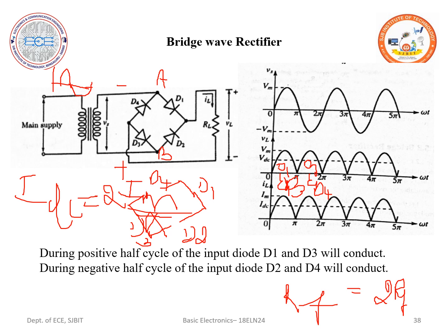So no matter what, the same steps hold good, but the only variation is we are going to substitute wherever we find RF with 2RF, right? So when we come to the efficiency, the very same efficiency is also going to provide you 81%. And similarly, when we come to the ripple factor, that is gamma is equal to 0.40.